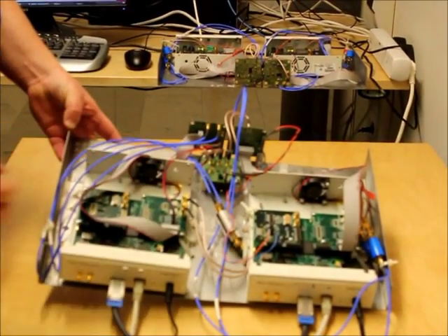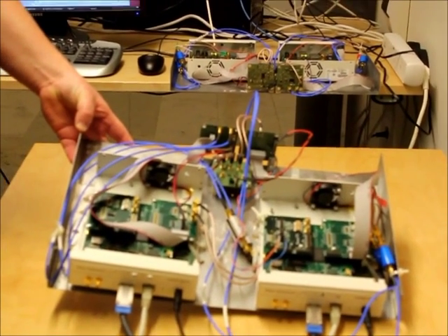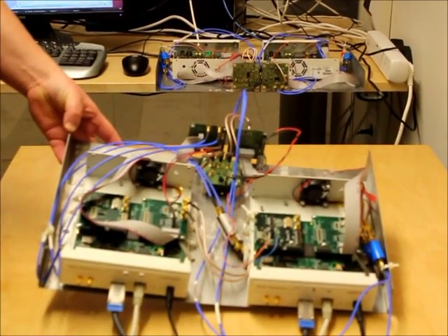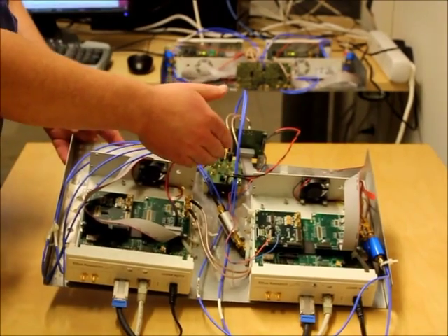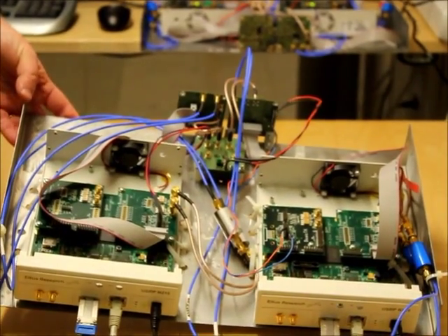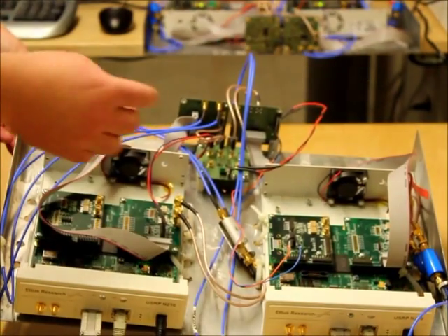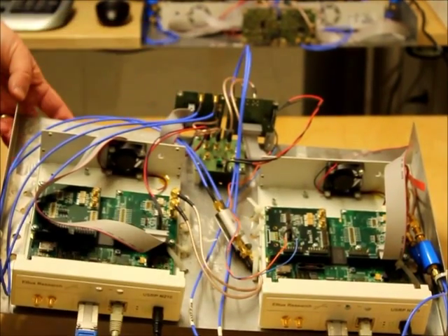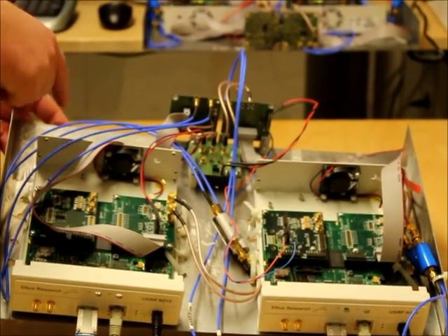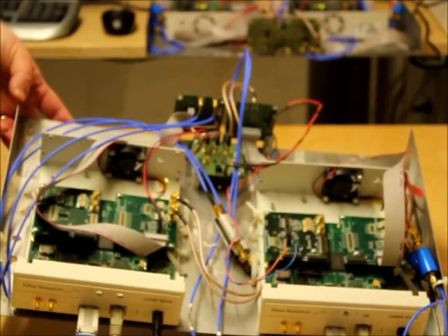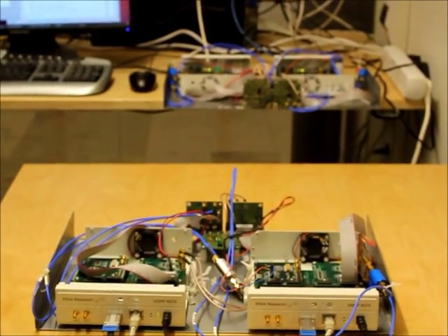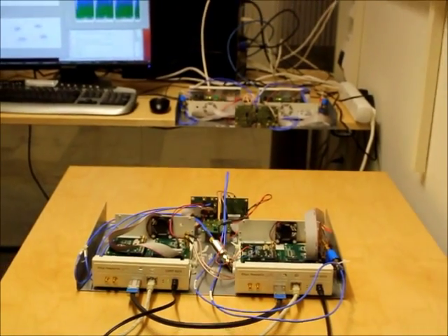In addition to the RF boards, which do the conversion between 60 GHz and baseband, we also have a clock board. This clock board distributes the clock, which is used as the input to the PLL of all the boards, so that when we use this clock board, the two receivers are phase synchronized. And we can have an arbitrary number of boards by daisy chaining these clock boards, because they have a chip on board with a clock, but they can also take an external clock and relay the clock to the next board. So any number of receiver and transmitter branches can actually be connected to this system.